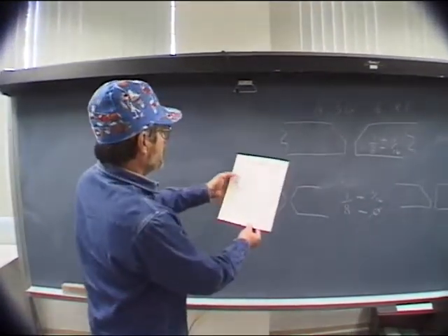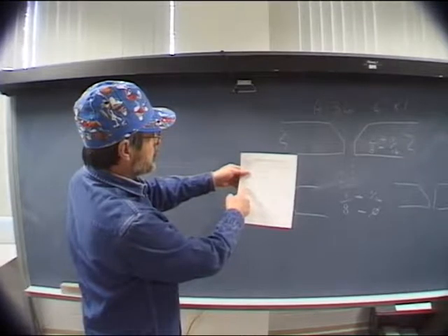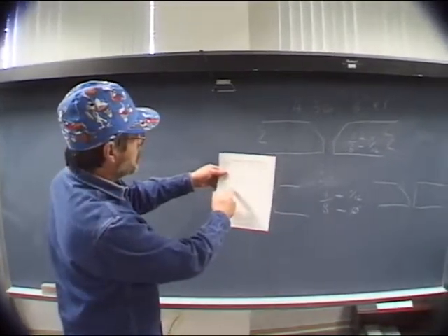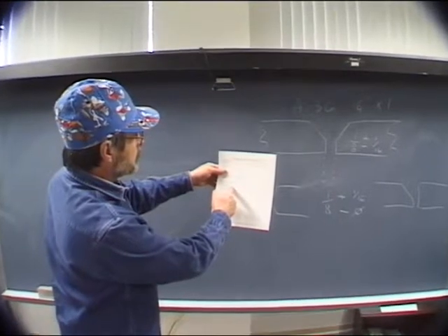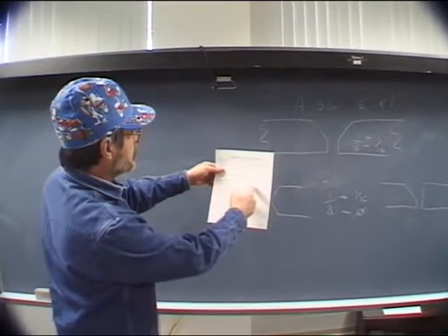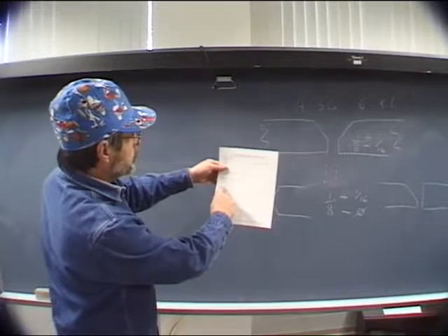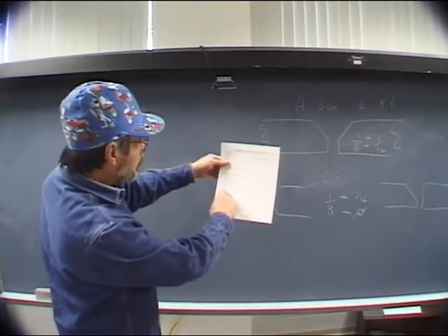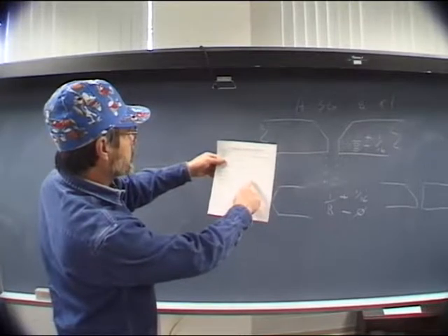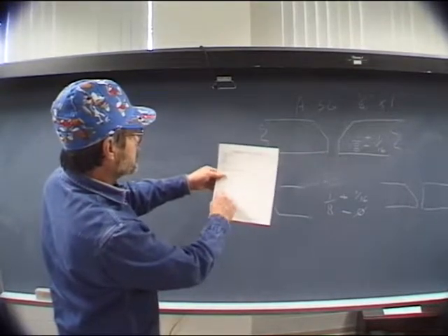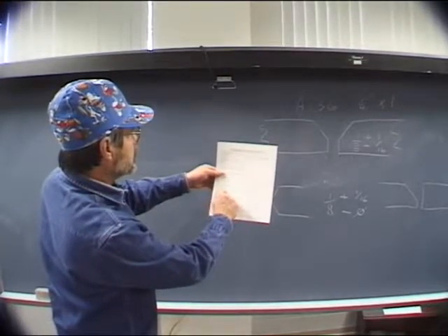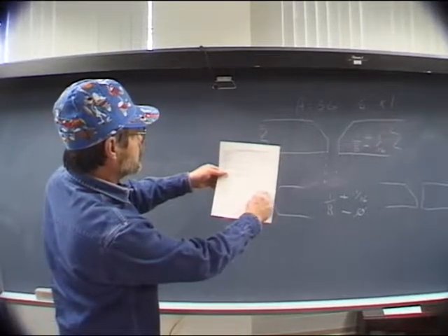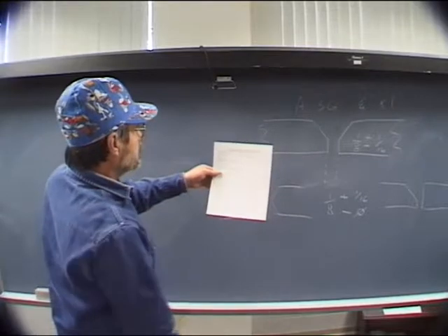Next, we have our base metals. P number 1, again, you can go back to that form I passed out earlier. P number 1, group number, I believe it's 2, to P number 1, group number 2. Or you can write in SA106B, or you could put the chemical analysis of the base metal. And then the thickness range of the base metal, whatever groove size it was, pipe size would be unlimited.